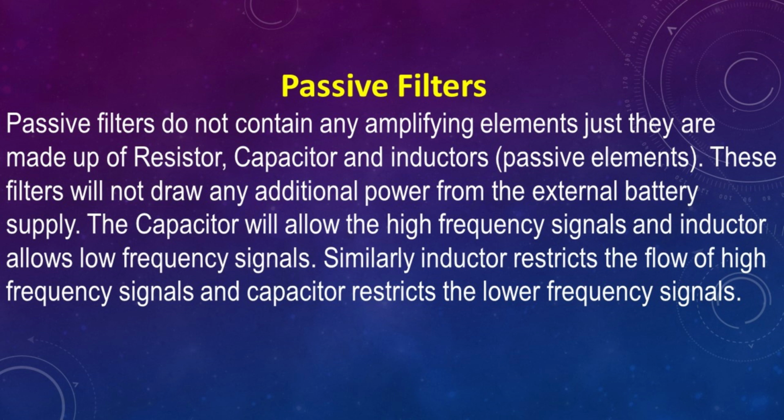Passive filters. Passive filters do not contain any amplifying elements. They are made up of resistors, capacitors, and inductors, which are passive elements. These filters will not draw any additional power from the external battery supply. The capacitor will allow high-frequency signals and the inductor allows low-frequency signals.